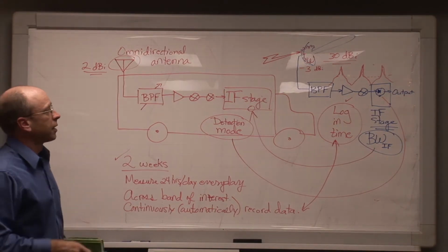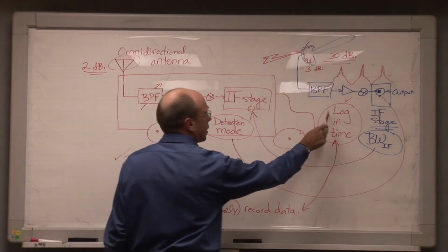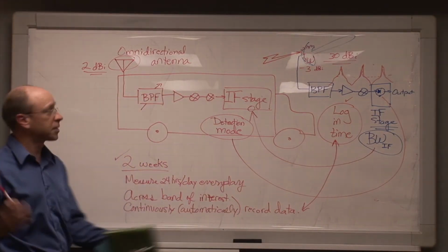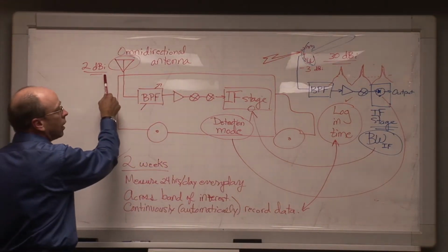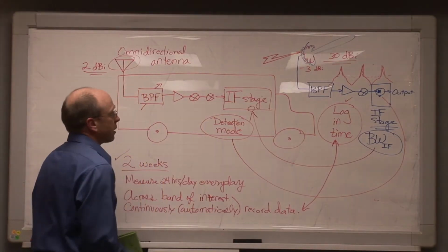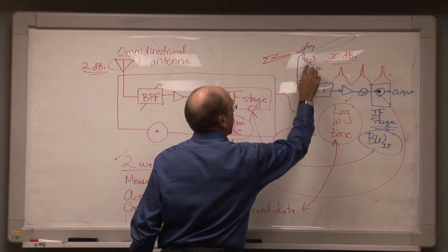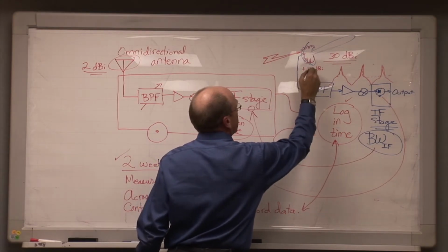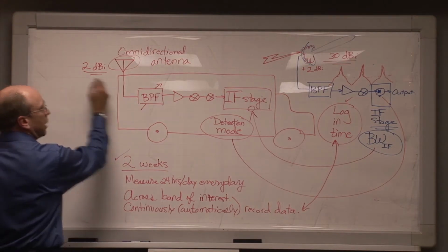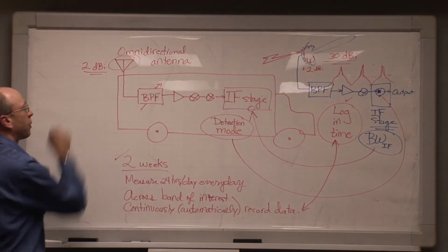It's pretty obvious, I think, to state that if they claim that they're seeing interference here and we're logging data continuously and we're not seeing it, and we have a lot more gain out toward the horizon than perhaps they have, we hope. And worst case scenario is these guys are running, by the way, say 2 dBi gain, say they have an omnidirectional antenna, then we're still equal in terms of antenna gain. We shouldn't be any worse, though.